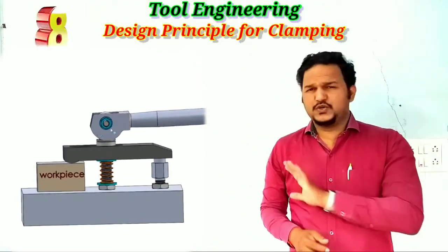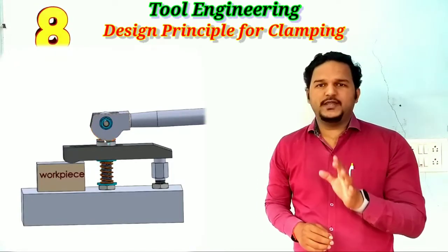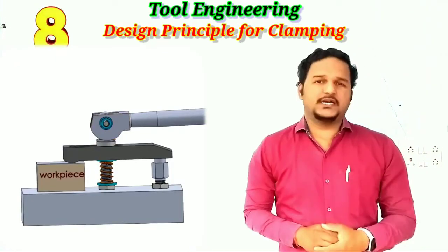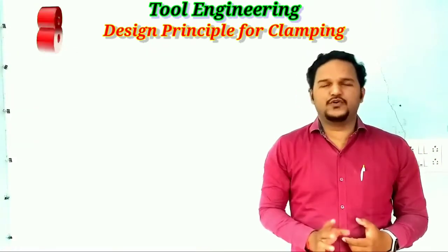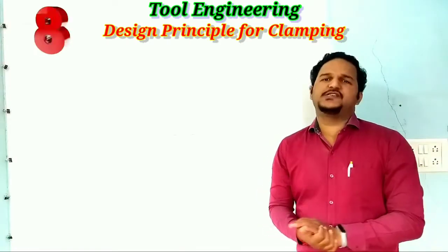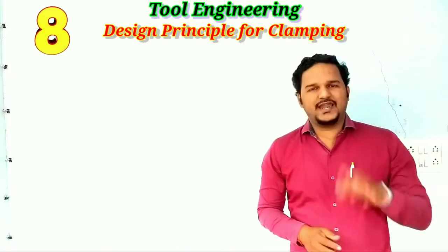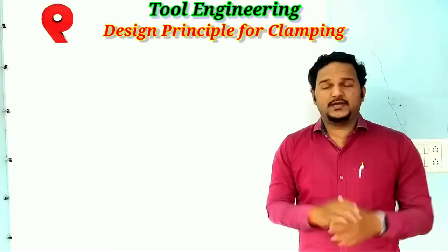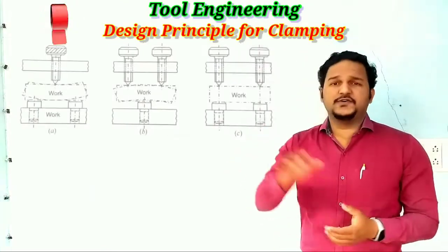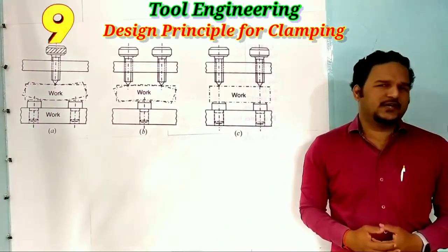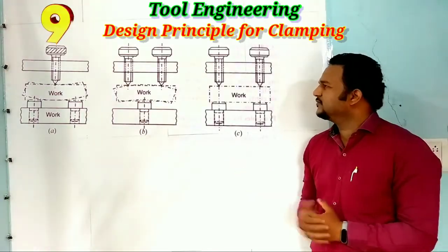Actually, clamps should never be relied upon for holding the workpiece against the cutting forces. The cutting force should be arranged against the fixed stop or a substantial part of the fixture body. The clamps should always be arranged directly above the points supporting the work. Otherwise, distortion of the work can occur, as shown in this figure.